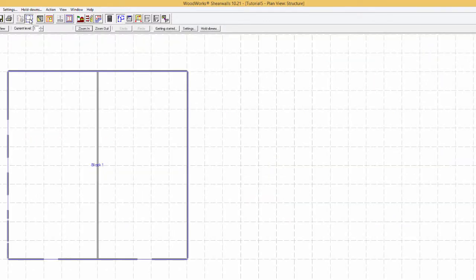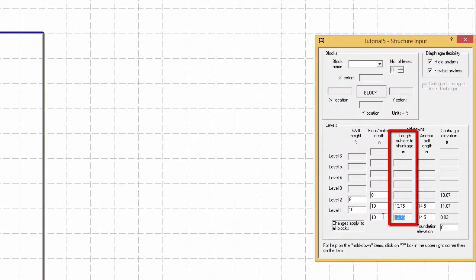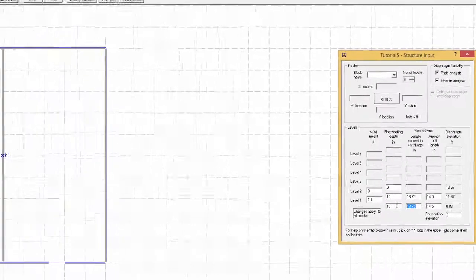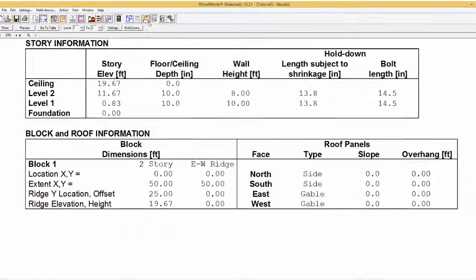If you cannot see the input form, simply select the Form View icon and it will be displayed. The program then uses the same method to determine the withdrawal design capacity as when the Include Deflection Analysis tab is unchecked, by comparing the fabrication and in-service moisture content to the same limits, smaller or equal to 19% or greater than 19%. Appropriate factors, taking into account the choice for in-service moisture and temperature conditions, are applied to nail withdrawal strength for components and cladding design and are shown in the Wind component and cladding design results table.